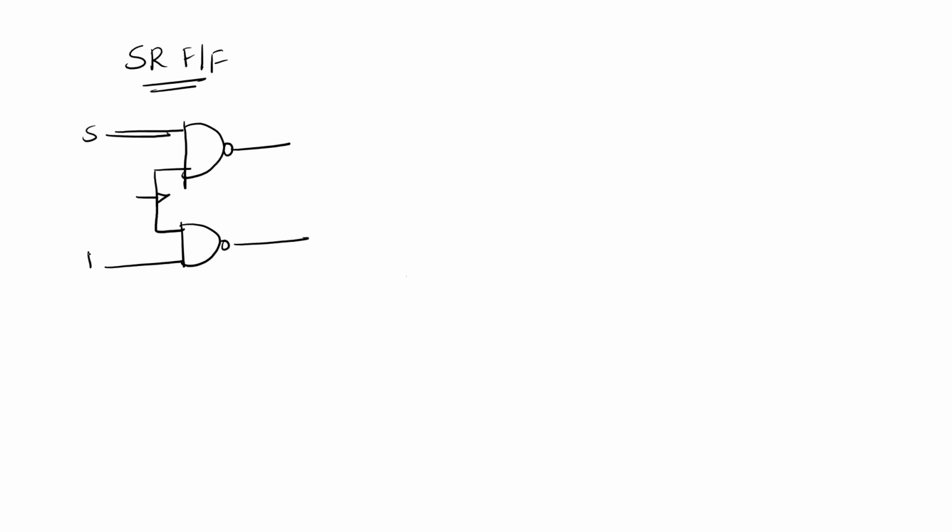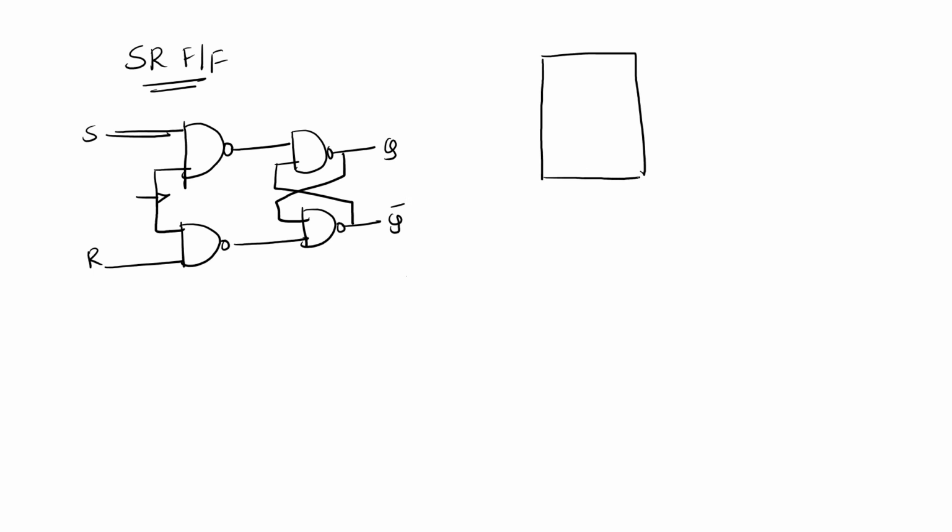This is S and this is R. And this is one more NAND gate, and this is one more NAND gate, so this will be feedback. And this is nothing but Q bar. This is S and this is R, and here this is Q and Q bar.